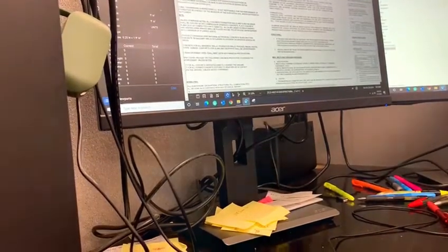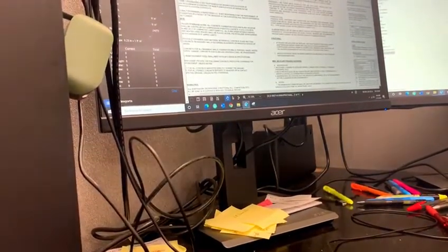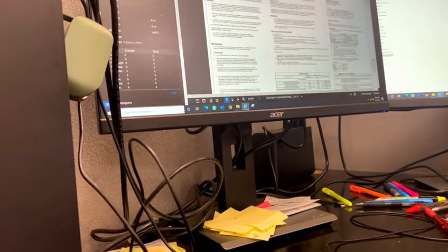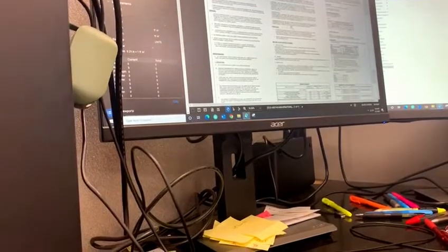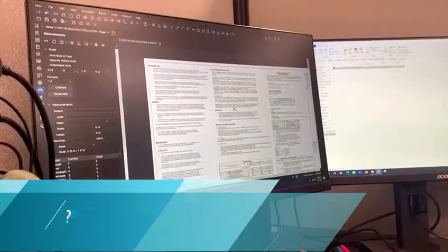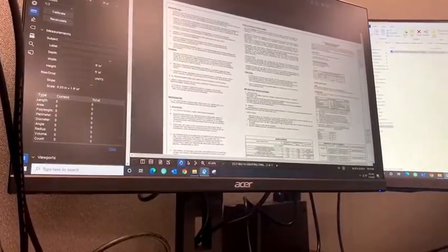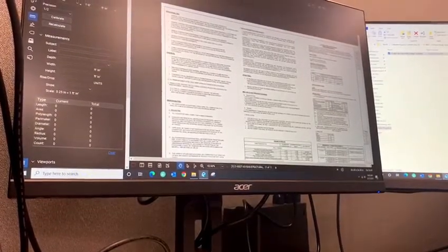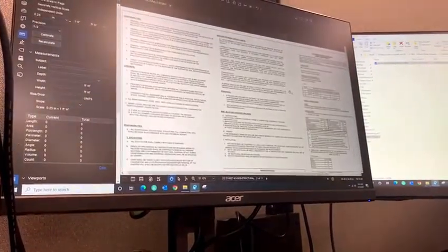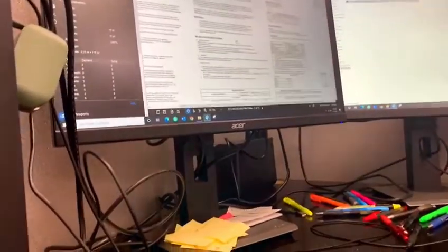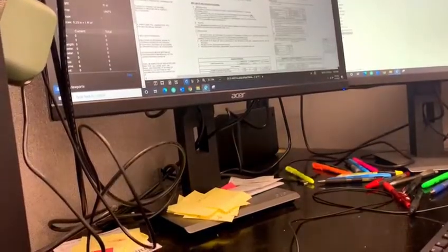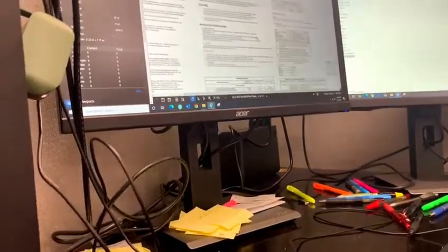Any exposed timber that's going to be exposed to the water areas to be treated. This is more important for piling houses. When we do stringers, anytime we do stringers, that has to be treated. Especially beach houses? Yes, sir. So the two examples I gave you, one is a slab on grade, and the other one's a beach piling house. Oh, beautiful. And I think that one's just a one story. I didn't get too crazy with that one. We leave the 48-story building for later. Yeah, exactly.